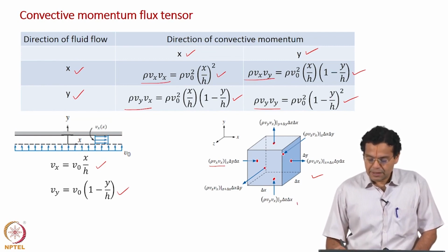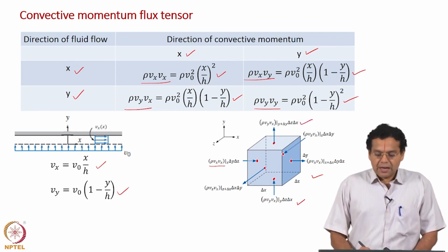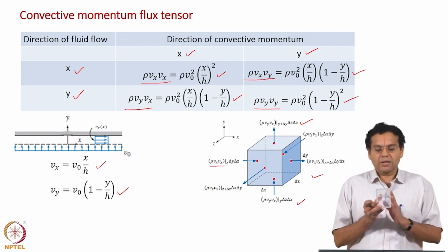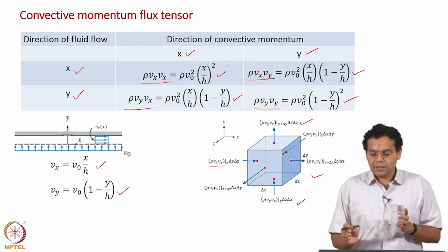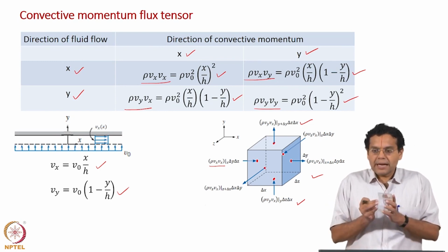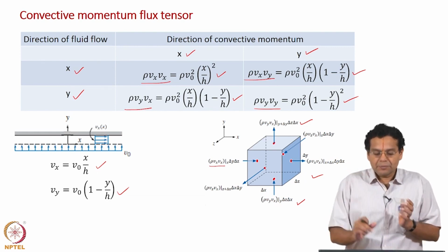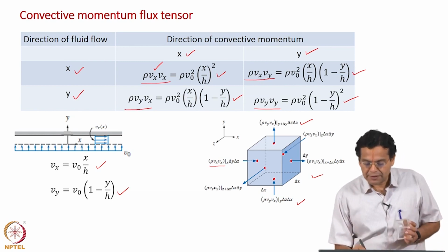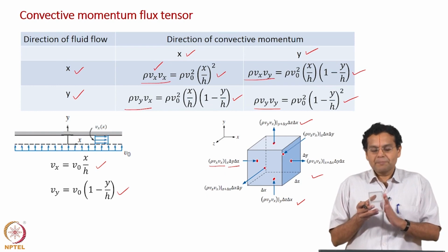Similarly, here it is the rate of momentum entering and leaving along the y direction. Those were for a control volume with one face here and one face here, where we talked about entering and leaving. Now we have reduced this to a small control volume, and they have become a point. So rho Vx, of course we do not have area here, so it becomes a flux, representing momentum flux at a point.